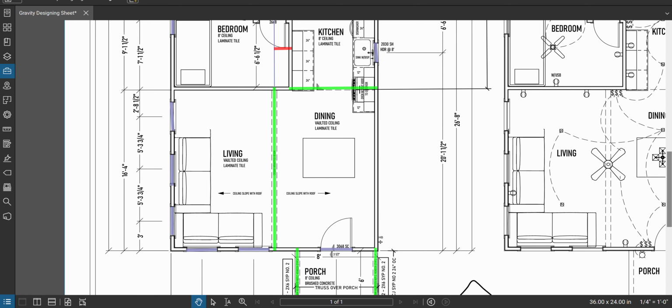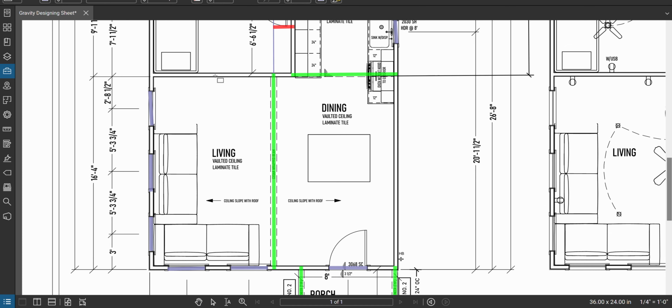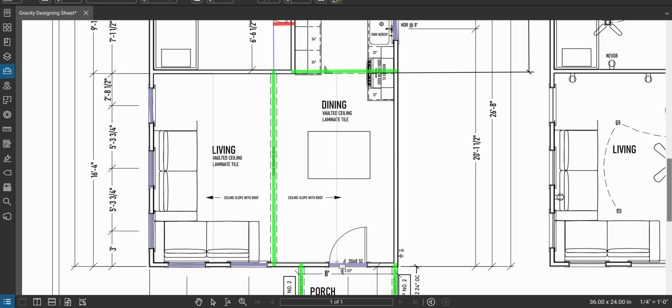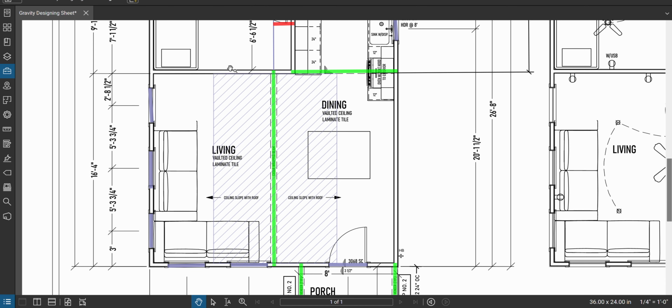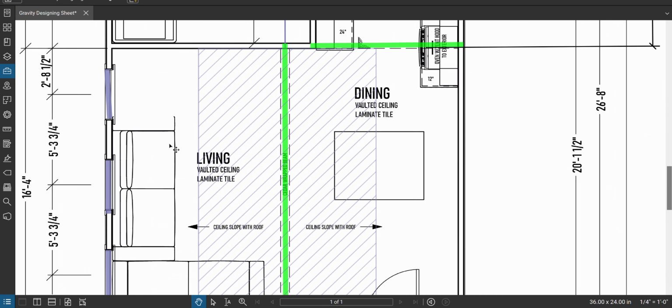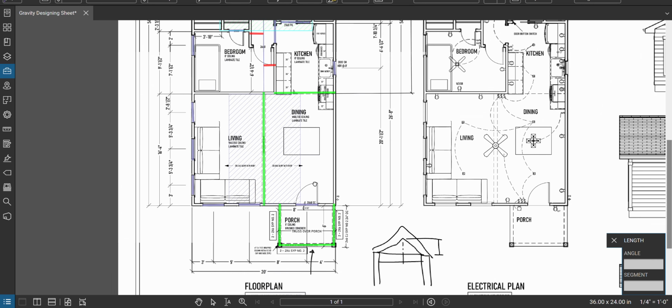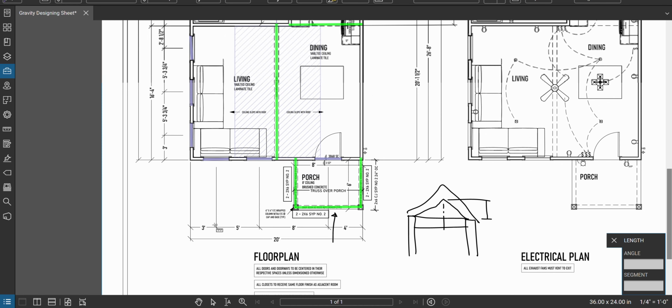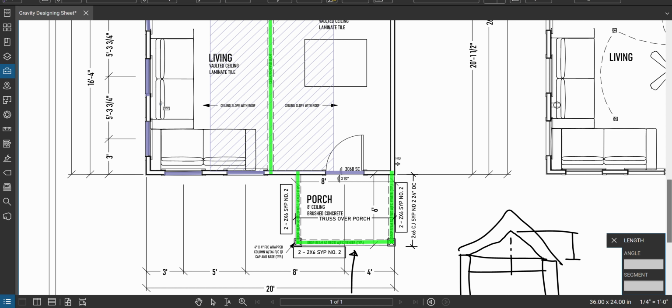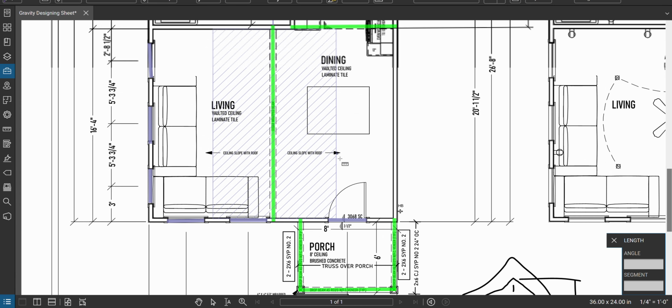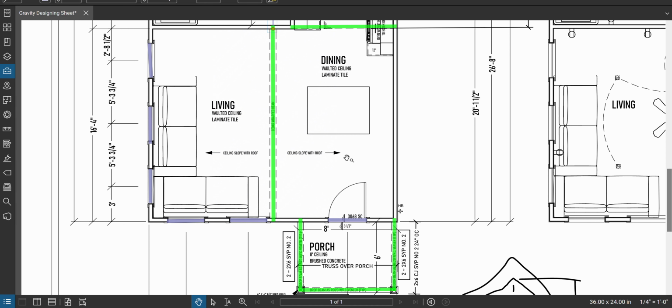So how would we do this? Well, what's the tributary area loading this beam? It's halfway between the beam and the support on this side to halfway between the beam and the support on this side, in the whole length of the room. Looks something like that. That's the area that this beam is holding. What's the width of that area? Well, it's pretty much half the width of the whole building, which is 20 feet. So we're going to be conservative and say yes, 20 feet, even though it's a little less because of wall thicknesses. So 10 feet. Boom. We've got 10 feet of tributary width of roof.